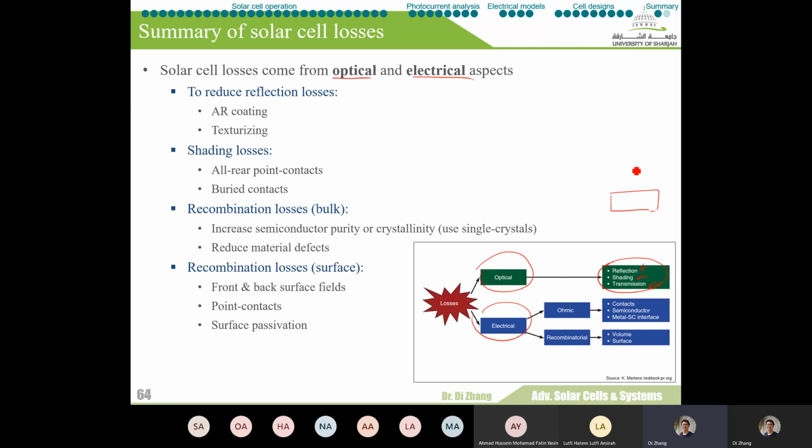So we said that in this chapter we taught you how to do the calculation for a typical solar cell material. Once the light is incident on the solar cell layer, part of the light will be reflected, and then inside the solar cell material, we understand from our theory that the irradiance is going to experience an exponential decay. Okay, so the horizontal axis is the depth of the material. So we're going to see exponential decay of the irradiance.